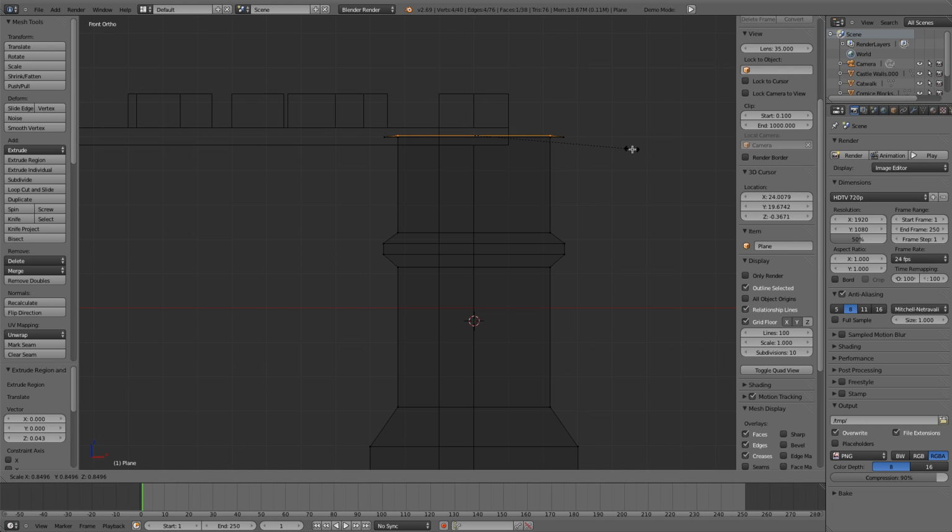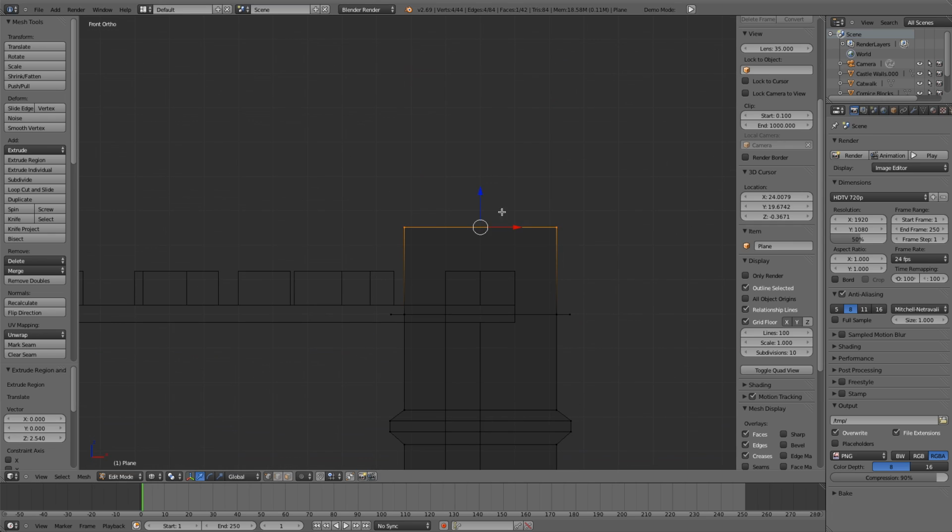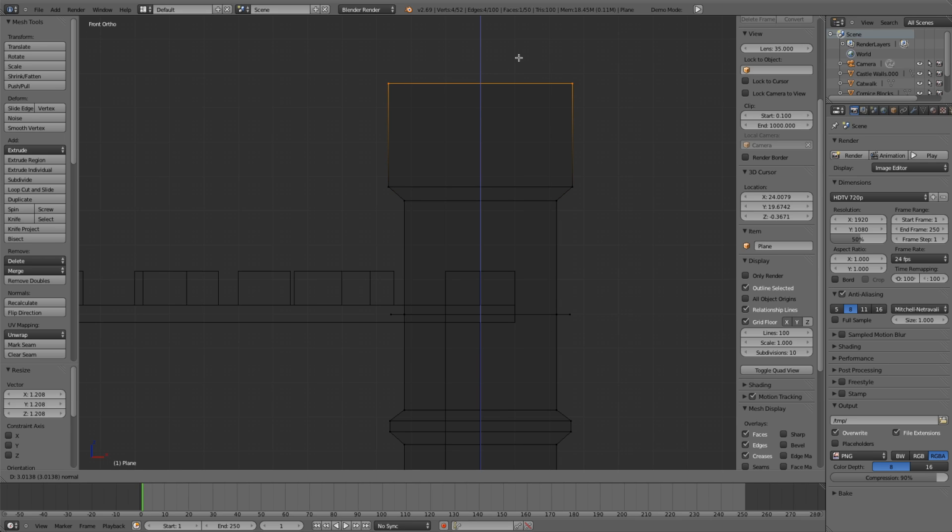So now press E to extrude and then left click as opposed to moving them, and then scale them down a bit approximately to where the long part was again, and then move them up ever so slightly with the blue arrow. Now press E to extrude and extrude them up approximately 10 Blender units. So now extrude it up a bit more and then press S and scale it out a bit as shown. And now extrude it approximately 3 to 4 Blender units again as shown.